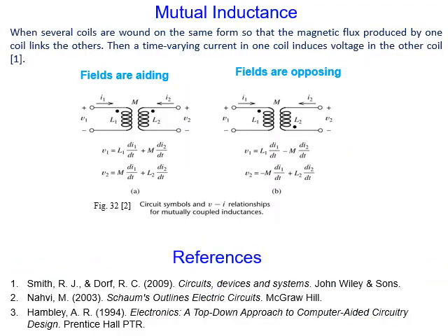Now, the last point here is the mutual inductance. You know, in a circuit we may have more than one inductance. When connecting inductances close to each other, the magnetic field of each one will affect the other one. So as an example here, this is inductance 1, and this is inductance 2. And the solid points here and here represent the direction of the field. Now for the first one, voltage v1 and current i1 apply across it, and v2 and i2 across the second one. If we want to find v1, we know that the formula says L1 di1 over dt.